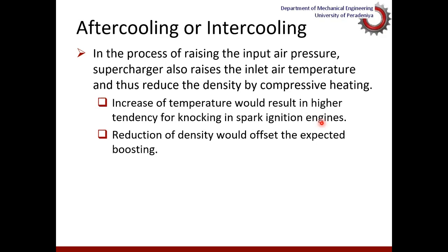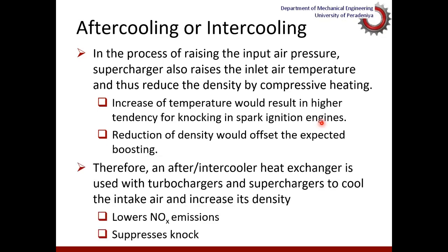And at the same time, increase of temperature would lead to increase of NOx emissions. At the same time, increase of temperature at the beginning of combustion would support the combustion process. Particularly, it will reduce the ignition delay and improve the combustion efficiency. Accordingly, there has to be a certain degree of addressing the issues or the disadvantages of this increase of temperature and reduction of density. One way of doing it is aftercooling or intercooling.